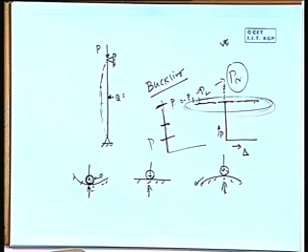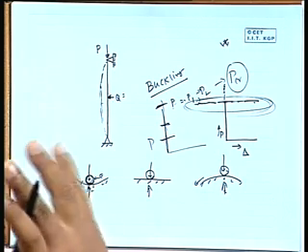Now that is the basic introduction of buckling, which is related to the failure of the long column. Here it is not material failure. What is the failure? It is geometric failure, right. It is quite long, and due to the typicality of its geometry, a very long cylinder type, it can't retain its geometry when some load is there. It is not due to exceeding the allowable stresses. So the material failure will not be there at first, it is basically geometric failure, but ultimately material failure will be there.